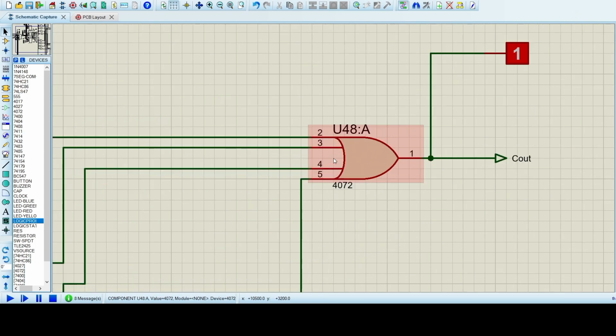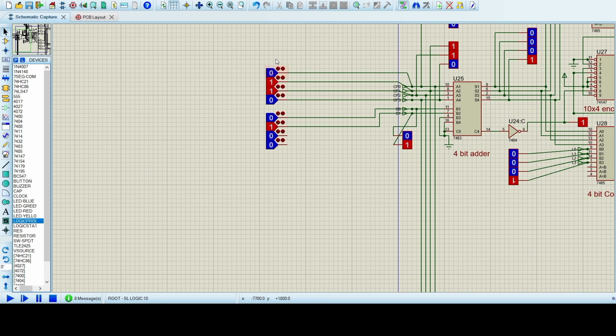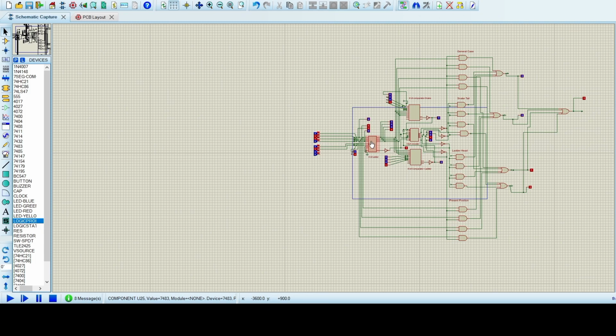And this OR gate serves a different purpose. First, when we began the circuit, I thought we could use the dice phase signal both as the trigger for passing the dice value and the present value to the adder, and for the updating of memory position as well.